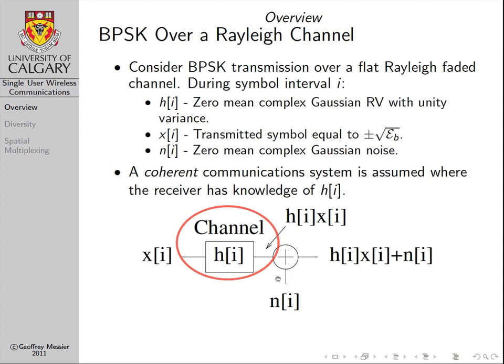And so that's fine, except that now we have this extra wrinkle of having this wireless channel here. We can think of the wireless channel as modifying the pulse shape of the transmitted information. At the input to the wireless channel, we have our original pulse shape. When it goes through the channel, it gets convolved with the channel response, and at the output of the channel block, we have our original pulse shape convolved or distorted by the channel, and we represent that by x multiplied by h.